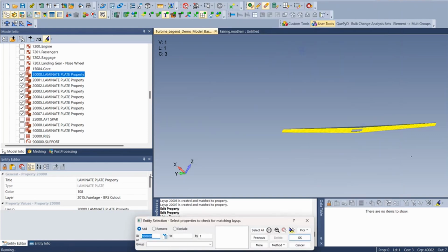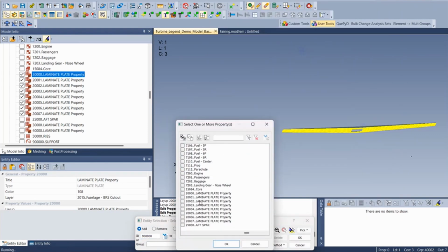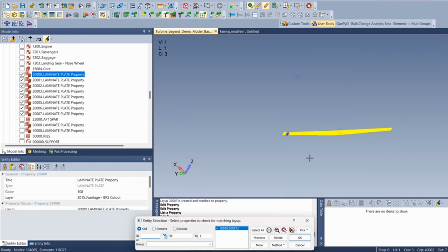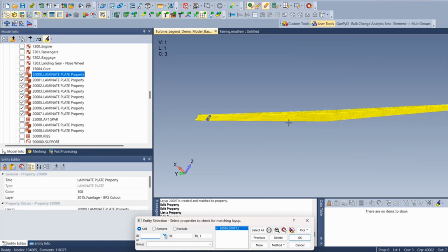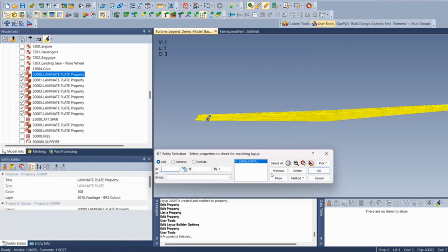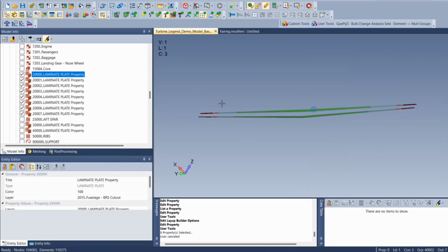Yeah. So I can ask about the spar, you have 30 titles called spar. Is there something that would be typical with a spar that would need every ply to have a title? That was just to help me, like P1, P2, P3, right? I mean, you look at a drawing, ply table, each ply has a ply number. Yeah, I use that for ply numbers. Okay, so you call it ply by ply number. Yeah. Then in the drop off, you see them disappear and stuff.